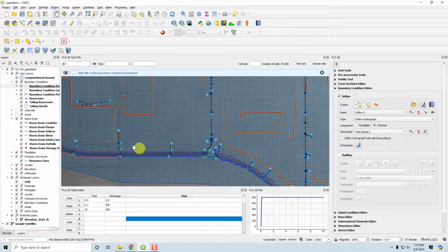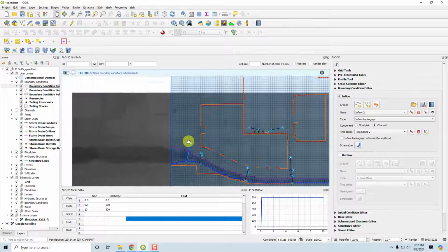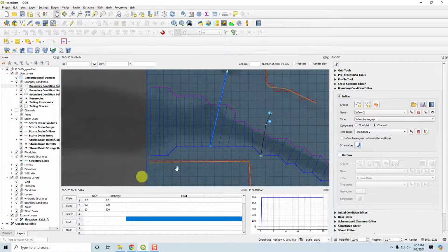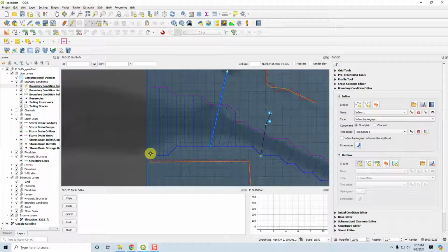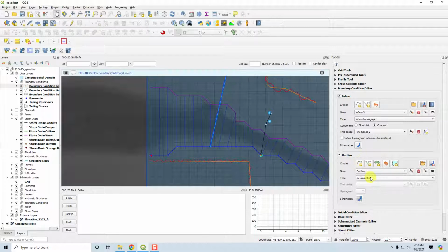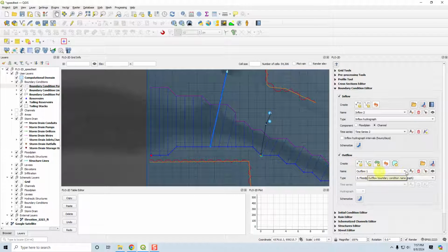Downstream controls. Let's go down here. We're going to build 3 different downstream controls. So typically, if you have a channel output, usually I like to make the channel flush with the boundary if possible. And then I will check the button and set the point. And again, remember, left bank looking downstream. And click OK, click Save. And this goes to channel, floodplain and channel, no outflow hydrograph.